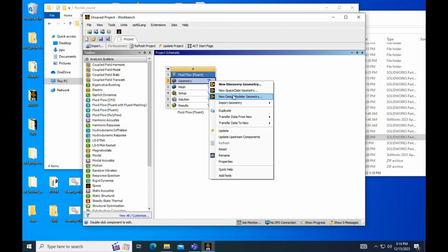When that's all finished, we're just going to double check again. Our move wall, that looks good. Domain 1, the region closest to the rocket. Domain 2, the outer region, the deforming mesh. Velocity inlet, pressure far field, and the pressure outlet. So that's all set. We're going to save the project.